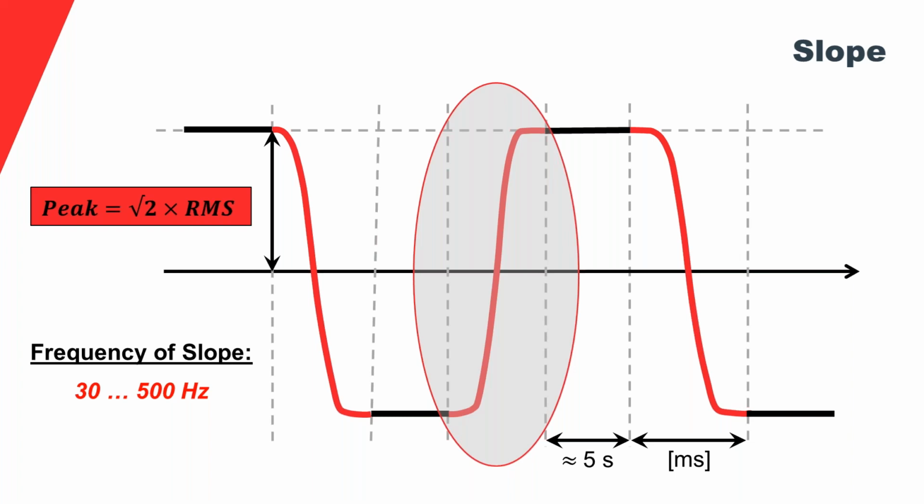So that's the reason why when you go to slope operation, let's say on one of our test sets, the slope is corrected by a factor of √2 to give you the right peak stress to initiate the same physics for the PD measurement. So there's a distinct difference between the VLF withstand testing and using cosine rectangular for the partial discharge testing. And that's perfectly fine.